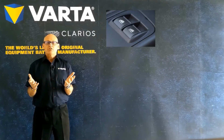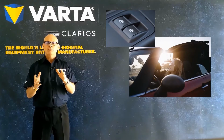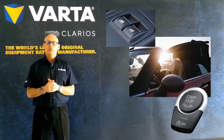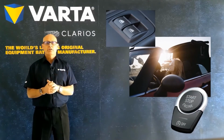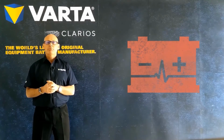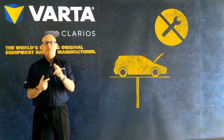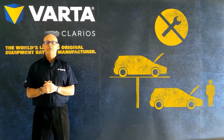Electric windows become slow to operate. Convertible roofs may be able to open but may not be able to close. Start-stop fails to operate, and the list just continues. These are all typical signs of a failing battery, so testing the battery at every opportunity has never been so important. Every service, any repair work, and definitely before any diagnostic work is carried out.